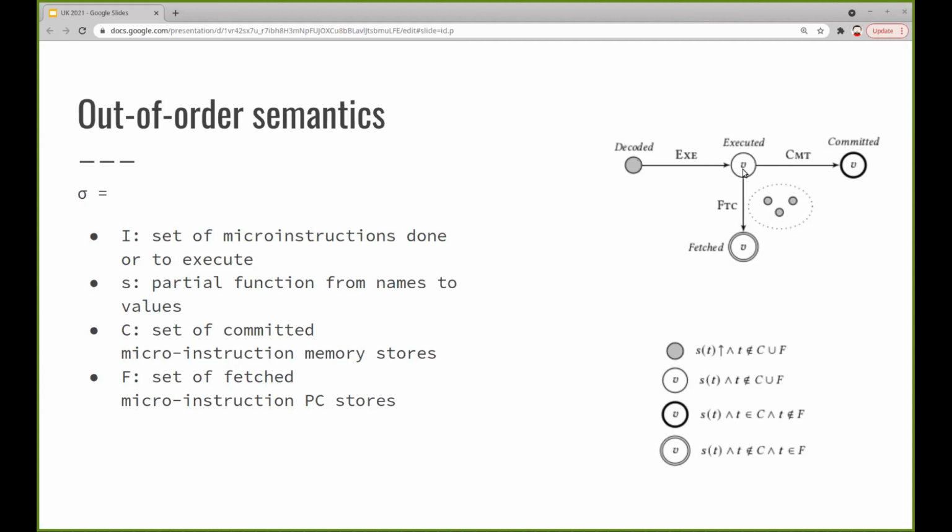This is especially needed in case of speculation, because you want to execute loads speculatively, but you cannot send stores to the memory subsystem until you have retired the instruction, because you cannot roll back what happened in the memory subsystem.